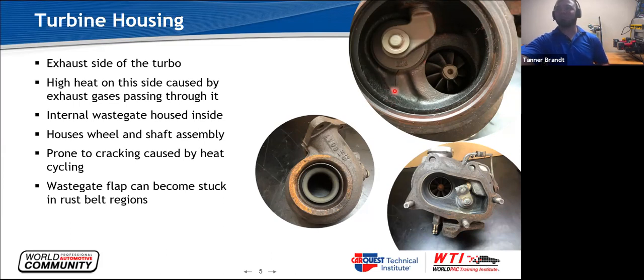But once these get to where you can look at it and say, like, one side of the crack no longer looks like it will line up with the other side of the crack, like more metal has broken away from it, that's when it's an issue, because at that point, now the wastegate is not sealing. And the bigger issue is that those small pieces of cast iron have now gone down into the turbo, or could have potentially gone down into the turbo. So that would be catastrophic. A turbo spinning at 200,000 RPM or 250,000 RPM, and anything that gets inside it is detrimental.